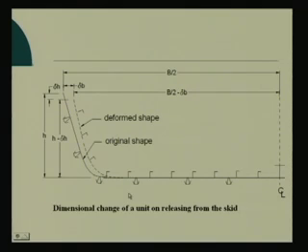Here when we talk about distortions, obviously we are referring to weld induced distortions, or distortions due to the thermal application because of the welding, right. So, we have seen how the distortions affect. Here is a sketch of a bottom part of a ship structure, just the double bottom unit.